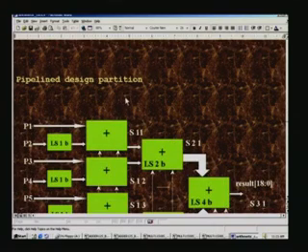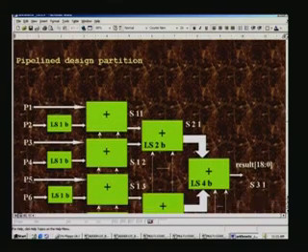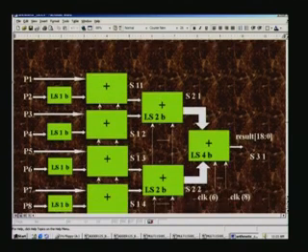So, this algorithm goes like this, it is pictorially depicted, and we have once again used bit partitioning as well as functionality partitioning, and here also the functionality will be basically add or subtract, and this is once again in 3 stages as we have seen in the adder before, and the only extra thing that is coming here is we need to do left shifting either 1 bit or 2 bits or 4 bits.